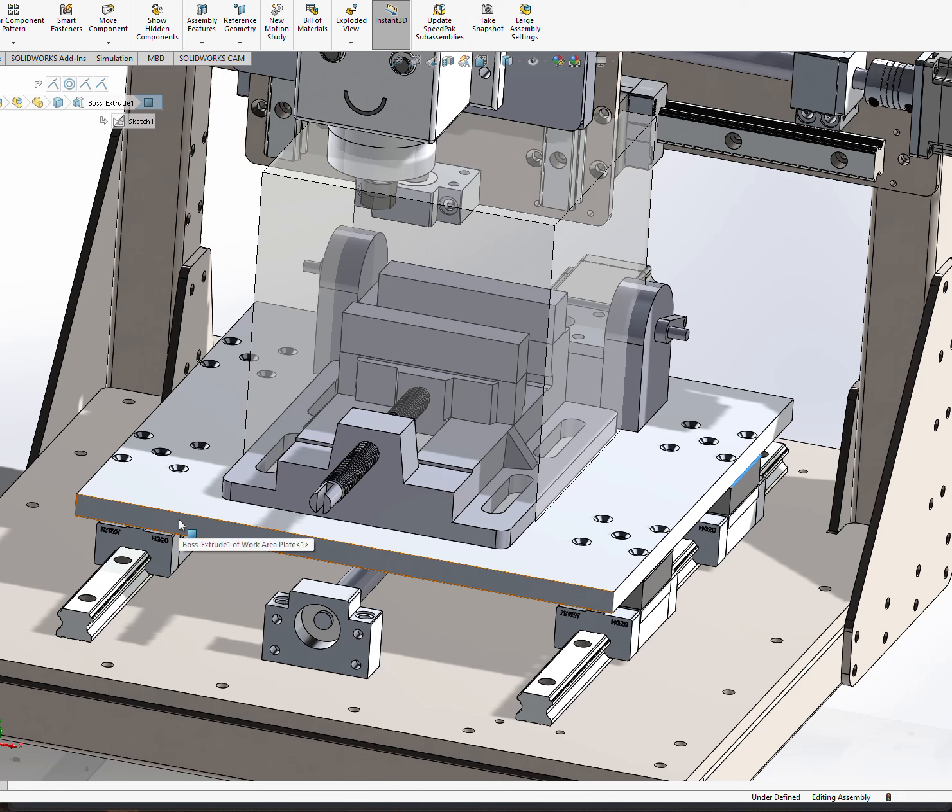In my mind, that is significant, and I see the 20 pounds of force that the milling is going to be doing, and I got that value from last year's MQP report. I see that as plenty of torque, also a reasonable value to not rip out the set screw. So I think we should be good with these values. I'm looking forward to doing the actual testing on the plate that's currently in the machine that we have from last year right now, and cross my fingers, hope all these calculations end up working out for us.